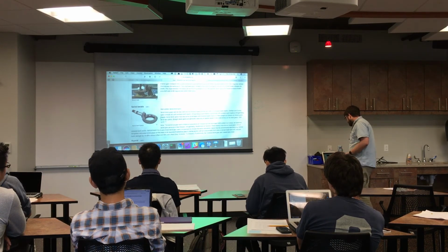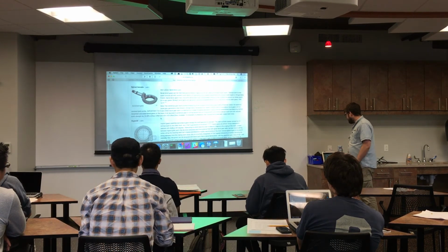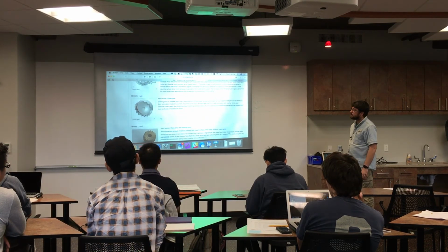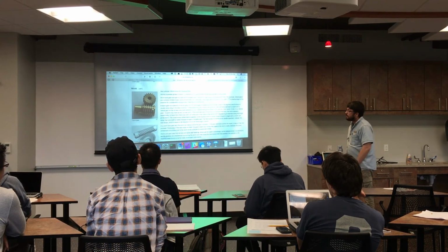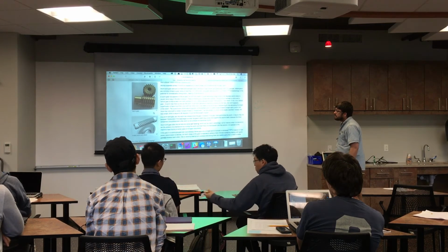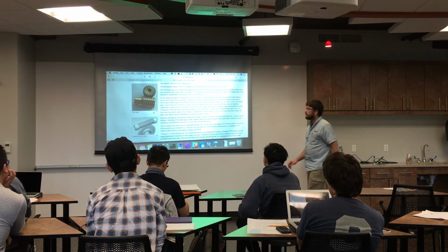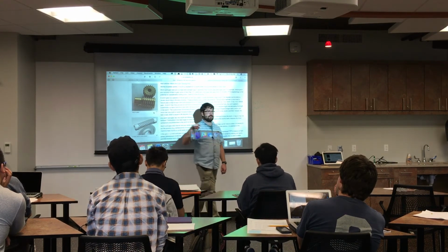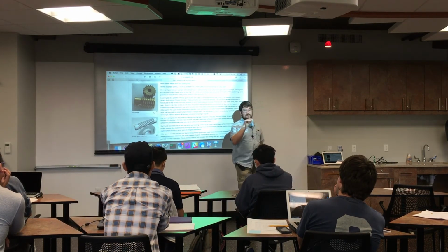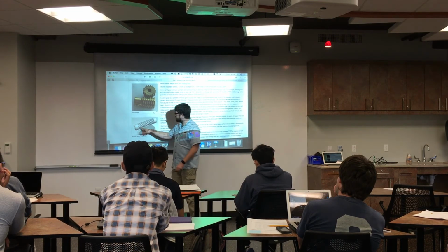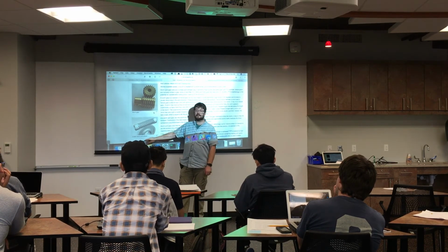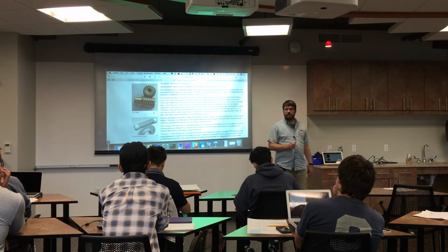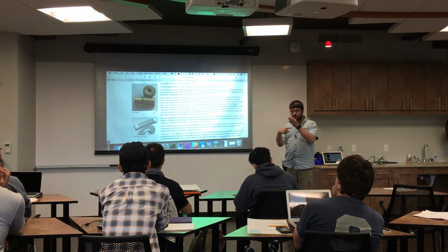So they're the regular gears that everybody's probably used to seeing. There are all these bevel gears you see commonly in car transmissions. This is a common assembly. I'll go down to the animation here. In equipment, worm gears. So this could be attached to a shaft that either a motor's turning or that you're turning with a knob. And for many turns of the worm gear is one turn of this big gear. So it's a way to do reduction generally and also change the axis of motion.